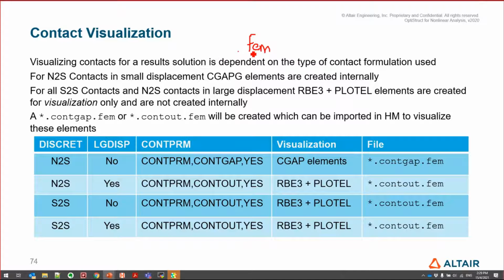It is generated automatically, and only if it finds that a certain area doesn't have contact. For example, if your slave area is this big and only part of it generates contact, we place all these grids or elements under a set that is stored in this .fem file. I forgot the name; it's going to be something like no contact .fem. So far we don't have anything on that. Later we can see if we have an example, and the name will be obvious.